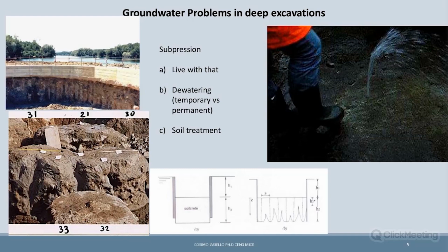Also, some standards, in particular the Italian, but also the Spanish, have some references regarding considering the jet grouting with some defects. So here, the area of the jet grouting should not be considered as it is in this A, but should be considered a bit less. This can also be done in our numerical analysis.